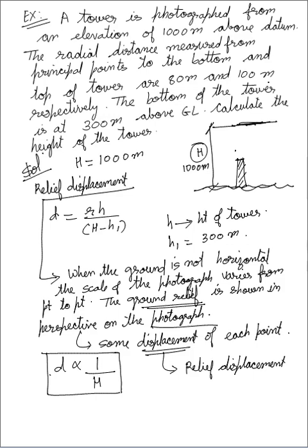So relief displacement is directly proportional to the distance from the principal point. These two things you remember.